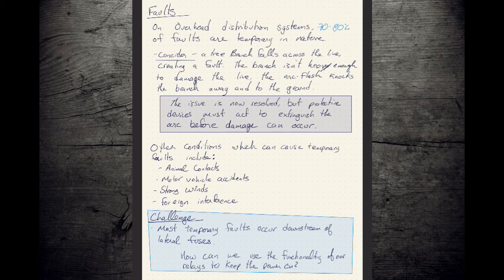And what that is, is those reclosers having detected a fault, and then they open the circuit intentionally to let that fault extinguish, and then they close back in again to probe to see, was this temporary? Is it tree branches or squirrels or strong wind? Or somebody threw some foreign interference, which is code for somebody threw some crap up into our lines. And so we probe at that and ask, is it temporary? A lot of times the answer is yes, and then it stops and all is good. But if it's not, eventually you've got to stop probing and just lock it out and be done.